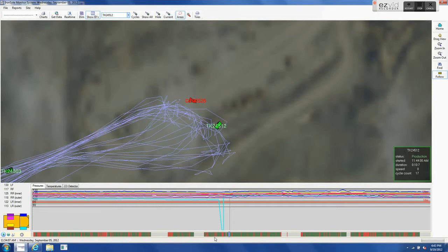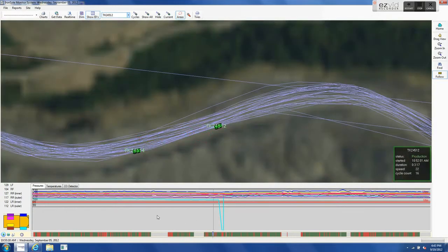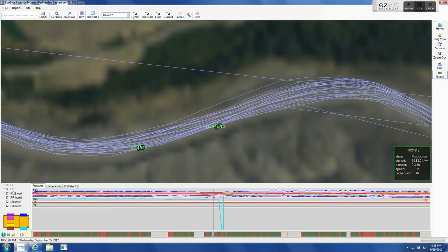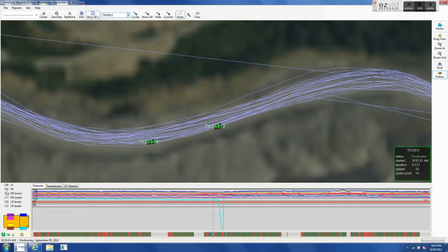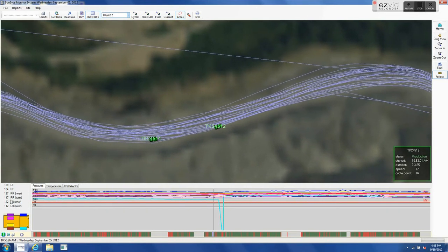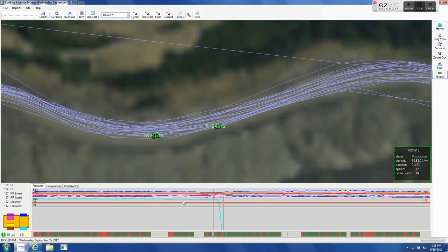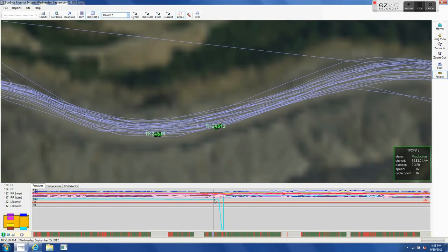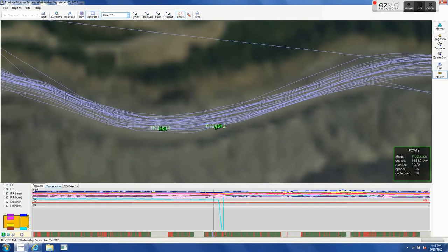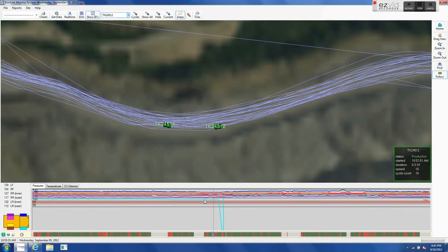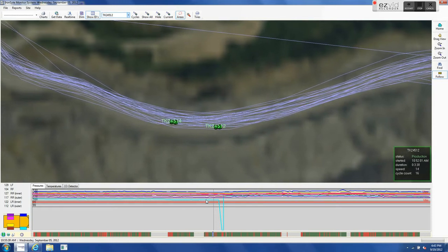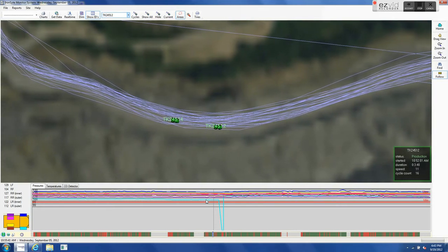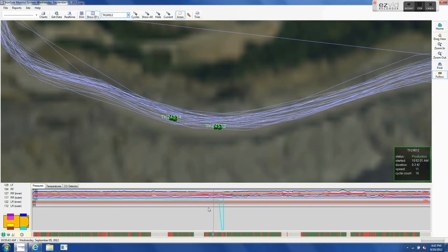And what you could see here from this particular unit is that the right front tire was below the threshold. It's reading 104. They'd like to keep that pressure a little bit higher, so we've set that limitation here. Once it falls below that level, we'll send a tire pressure alert out to the tire man's smartphone on the job.